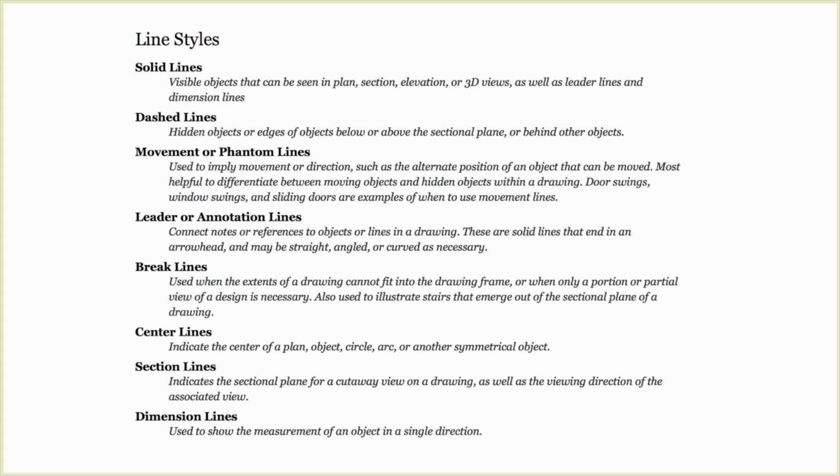What I mean by a break line, and you've seen this before, is when you're drawing the line and it has that little, kind of like a heartbeat line. And typically there's two lines that go together like that. It's hard to do it. It's two break lines, and the idea is that the drawing stops and then continues, and you've cut something out of the center. And so that's an important line when you have too big of a drawing to show. So you want to show that this little piece connects to this little piece, and there's some lines that go in between, but we're cutting those out. So we do those little break lines there.